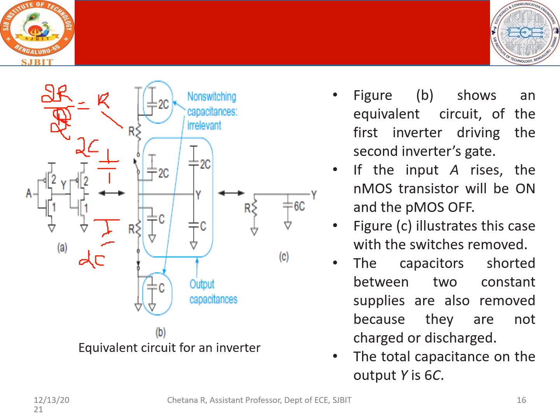Next, we have the next device, which is the load, which is given here with 2 and 1. So when you again replace this, you have the resistances and capacitances, but for the load we will be considering only the output capacitance. So output capacitance is given by C, 2C and C. And for the equivalent circuit of this, since this is connected to VDD and this is connected to ground, they have very little role in terms of charging, therefore this can be redundant. Now how many capacitances do you have? Diffusion capacitances are 2C, 4, 5 and 6.